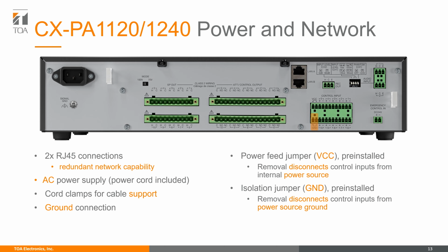In most cases, you'll leave these jumpers intact, but every now and then you might get noise or hum over your audio lines if devices are connected via these control connections to other systems. This is an issue that is common on PA products in general. If you encounter such situations, removing the jumpers can alleviate these issues.